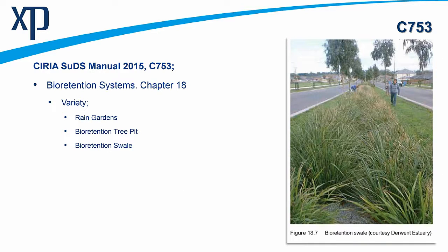We could look at a bioretention swale, so a longer linear structure. And the other thing that I'm interested in here is not necessarily introducing the flow right at the upstream end of this swale as a runoff from the development, but the lateral flow coming in off the highway as we come down along the swale. I want to better represent and model and design with the lateral flow running across this grassy strip and then entering into the bioretention swales. So down beneath this swale, what's the difference between this and a regular swale?